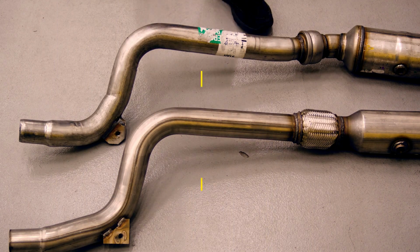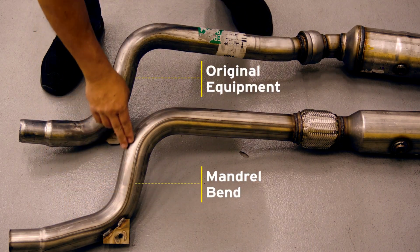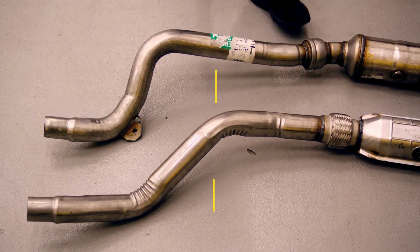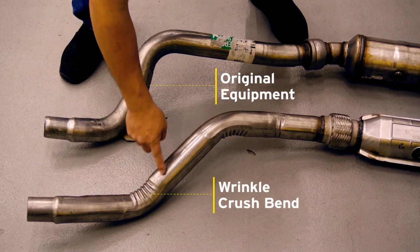MagnaFlow maintains the OEM design, flow, and geometry in our converters by utilizing the same mandrel bending process. This allows the MagnaFlow part to demonstrate similar flow characteristics of the OEM part, avoiding a negative impact on fuel economy or engine performance. Most aftermarket catalytic converters are manufactured using crush bends.